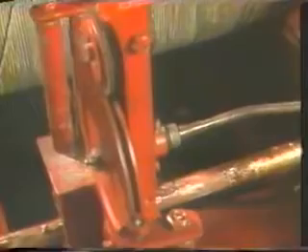Immediately after leaving the wireline reel, the wireline is looped around the counter wheel. The wheel is precision machined so that when the wireline is wrapped around it, the circumference of the circle measured to the center of the wireline is exactly 2 feet. There are counter wheels machined for each size of wire.